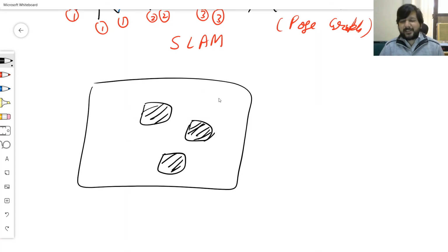So SLAM is the first thing to do, and what it does is that as long as my robot starts from the charger, it can always use its previous position to calculate its new position using localization and this known map. If the robot doesn't start from the charger, it won't be able to solve the correspondence problem. It will look at the corner, but it will not know which corner it is looking at, so it will not be able to eventually solve that problem.